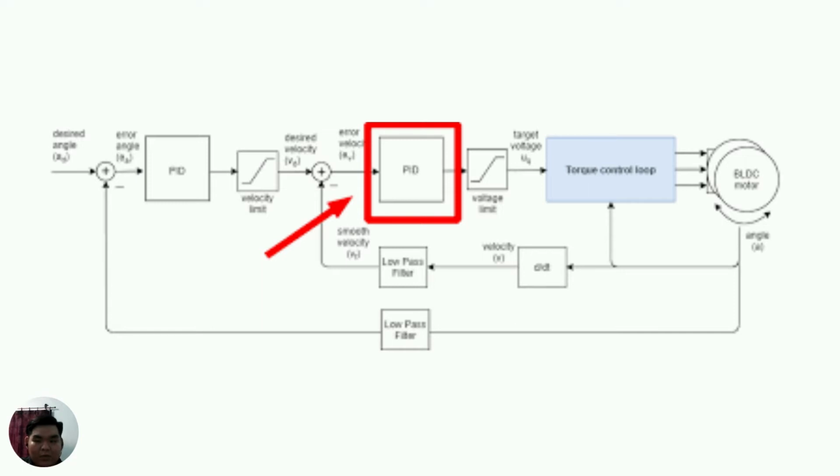Kp is the controller proportional gain, Ti is the controller integral time constant, and Td is the controller derivative time constant. Given measured feedback loop parameters, the period Tu of the oscillation frequency at the stability limit and the gain margin Ku for loop stability, the goal is achieving good regulation, so it will reject the disturbance.